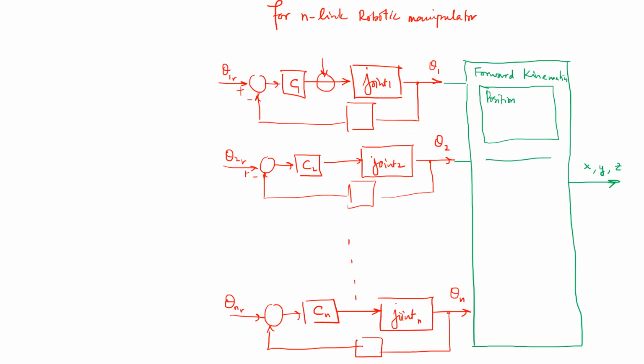There is going to be another module corresponding to velocity. So forward velocity kinematics is going to be handled in there as well. And that is going to produce the x dot, y dot, and z dot, stuff like that. But it will require this information given to it in terms of theta dots as well, like theta 1 dot produced over here. So when the speed control paradigm is implemented, you are going to get the information corresponding to the angular speeds, theta n dots. So these are going to get into the velocity block, and they will produce how the end effector is having its velocities executed in the task space. And similarly, if you are going to need the acceleration, that will be added as an additional module in that.